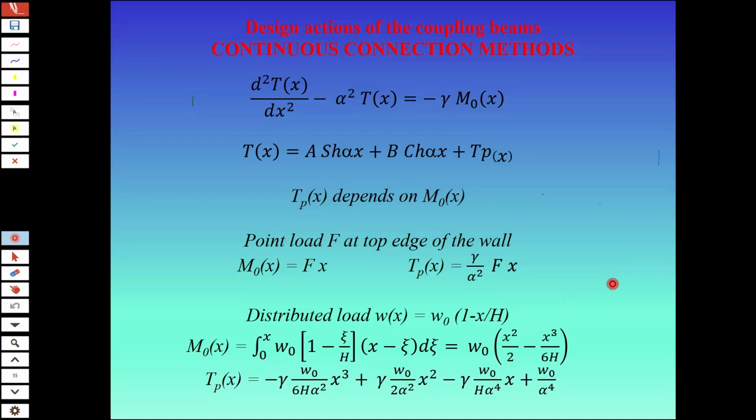For the beam, once you have the width of the column, either if it's cast in place or precast, try to keep the width of the beam the same as the column. If it's cast in place, it will guarantee easy formwork. If it's precast, it will guarantee uniform distribution of stresses. What about the depth? Well, if you are cast in place, start with 1/10 of the span. If it's precast, we have already seen, for example, with a pre-stressed element, the typical ranges. So these slenderness ratios are numbers that you have to start working with.